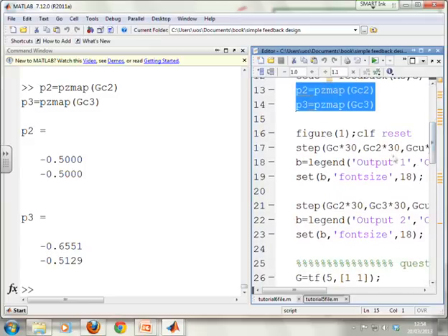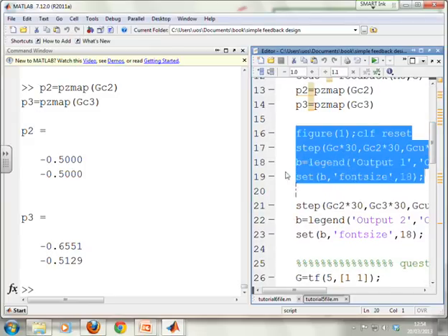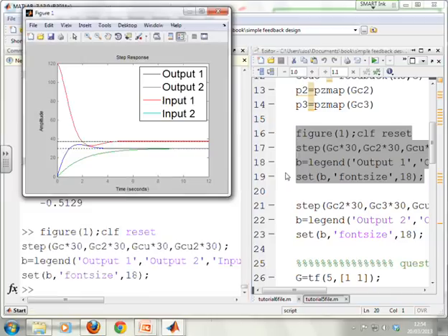So now let's look at some figures and see, does this do what we expect? So first then, this one looks at the original compensator and the heuristic compensator. The original compensator, can you see that the proposed input goes up to 120? Very, very large, much, much bigger than the steady state. And remember, we actually had a limit of 50, so this couldn't be delivered in practice. With the heuristic, we have the input, you can't see it very well here, it doesn't change, it's like a step, it's just constant all the way along.